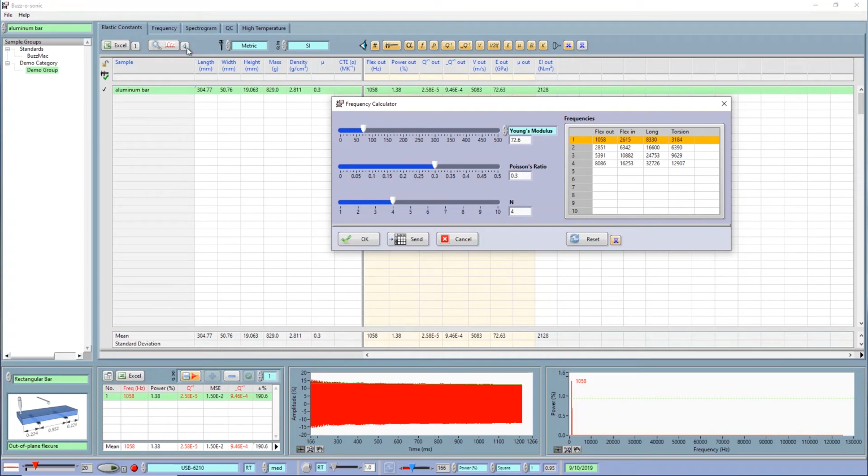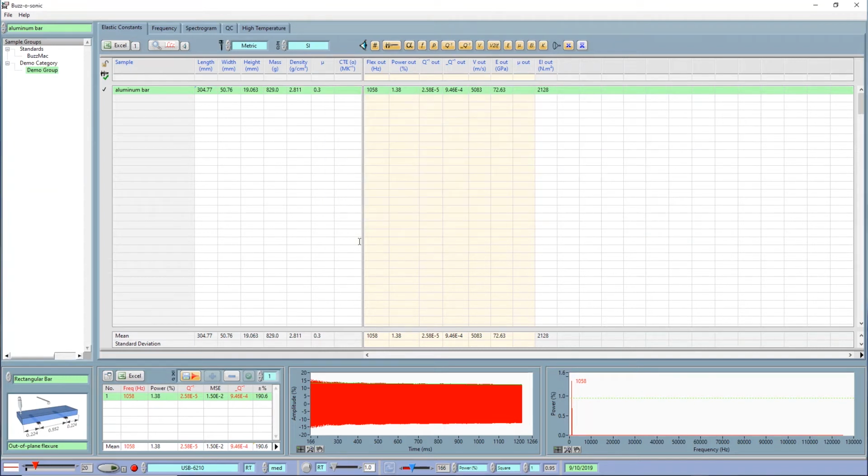Oh, by the way, you can also show these curves, I mean the expected frequency on the spectrum. If I go to the next line, you can see how we can identify. This is one good way of identifying peaks in the spectrum. Now if we don't want those on there, we can just turn them off there. So we know it's around about 3000, we can either OK or cancel it.